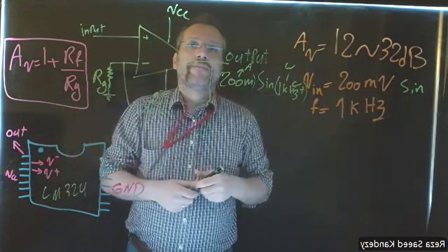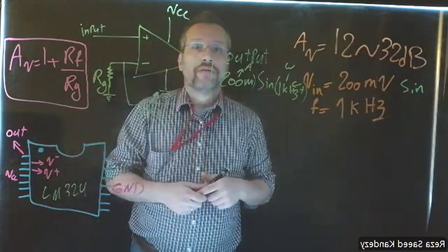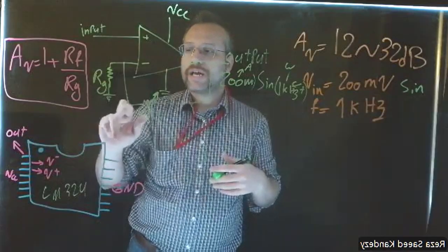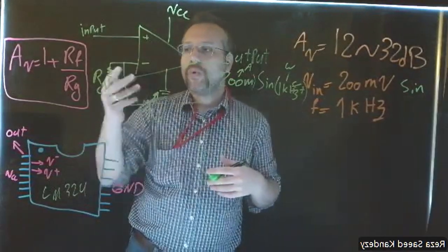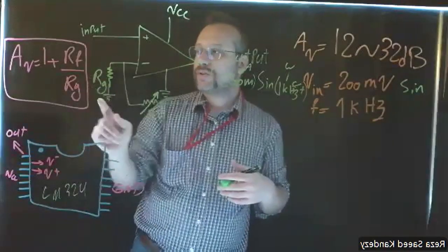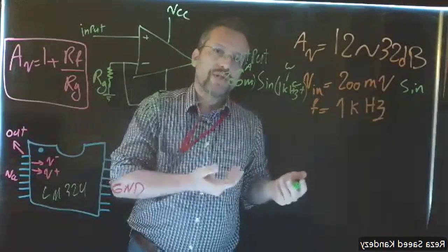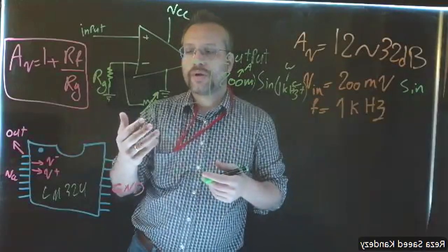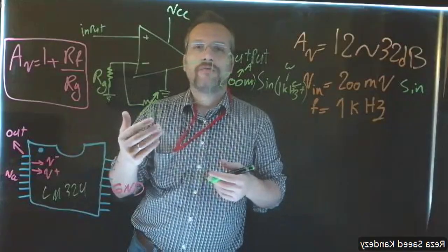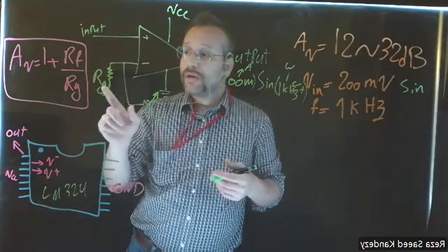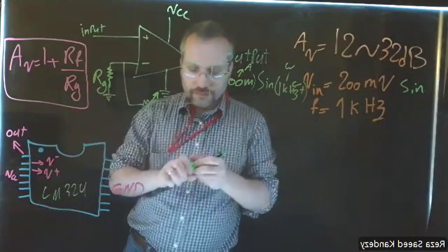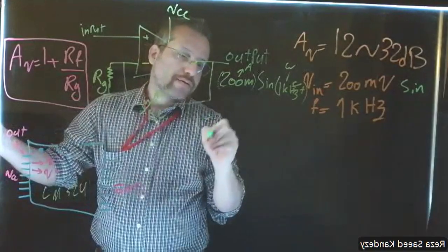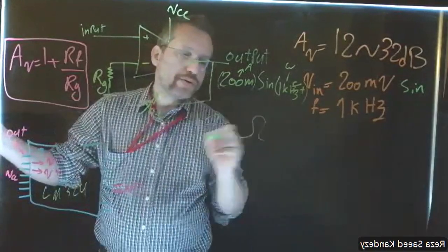As I said, I have a limitation in my inventory. So the way I'm going to do that is I'm going to set one of the resistors, this constant resistor here, to one of the resistors that I have in my lab, and then find the values for the feedback resistor. The resistor that I have is a 170 ohm resistor.